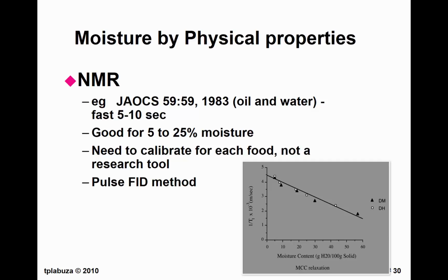Now, the last thing, we have 5 more minutes? Yep, 6 minutes. I would like to have a system that I can put on a line, and I did a lot of work with Ocean Spray on the Craisins. You have Craisins coming out of a drying oven, in a pile 6 inches deep, and they wanted an automated system. The first thing I said was, let's go to 2 inches deep, because you're never going to get a good measurement on that.